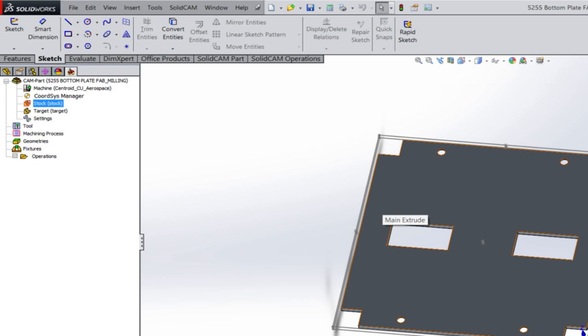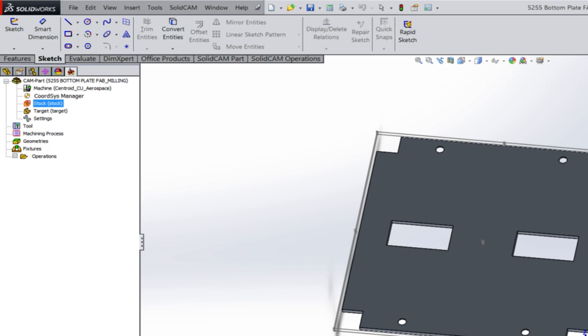Really, you shouldn't even leave just only 1 on there, because then you can rotate. You should really leave 2 clamps on at all times. So you might consider taking this one off this corner and putting it right here, taking this one off this corner, putting it right here, and then you can remove your last two. Okay, questions on coming up with a plan before you start machining?